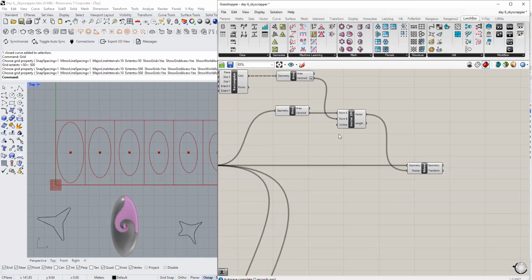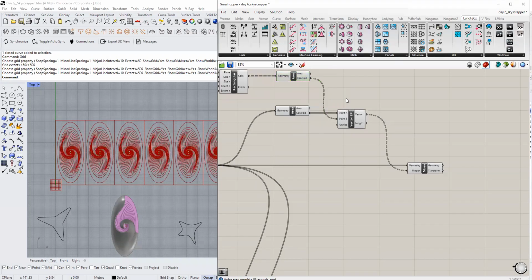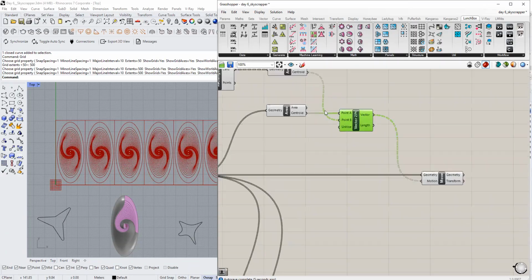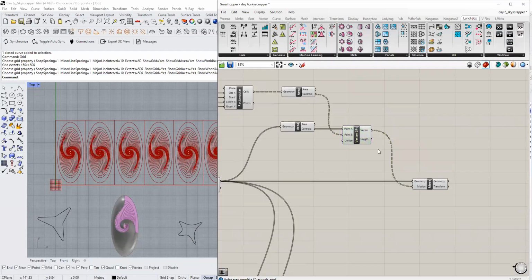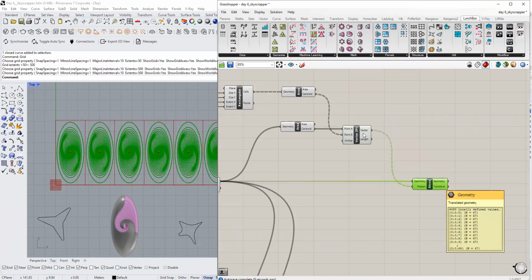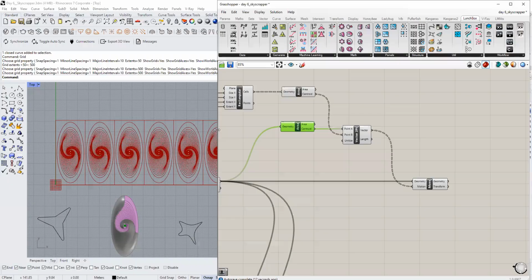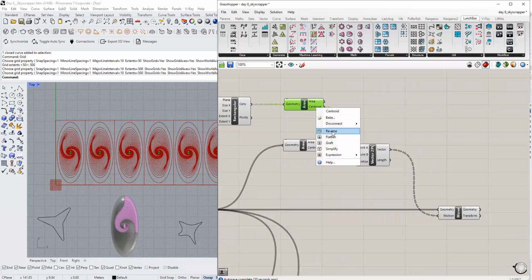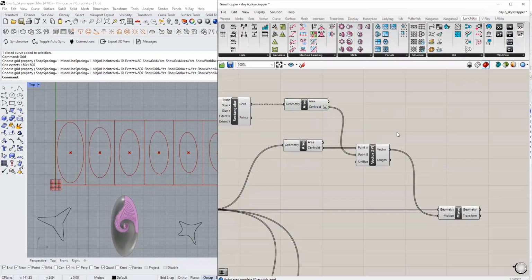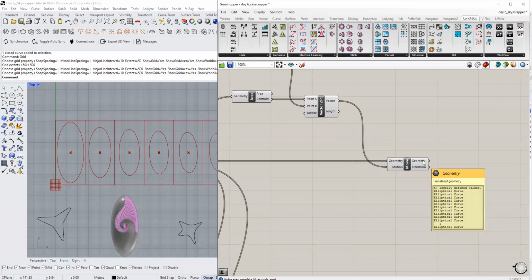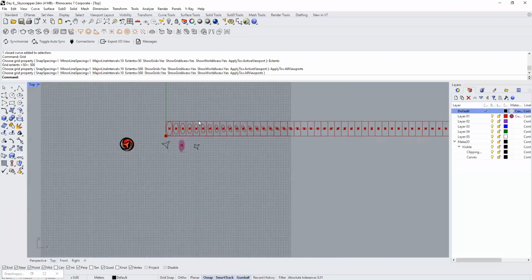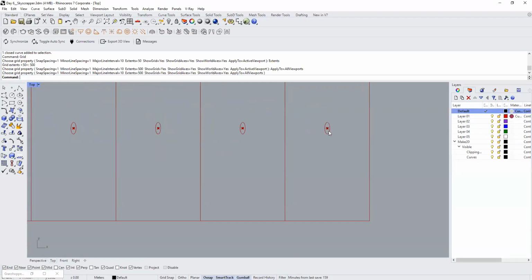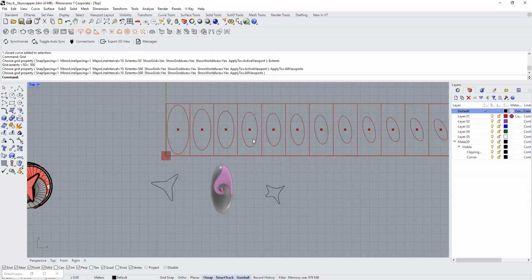That's it. So as I said, when you see this problem in multiple components, you can either go with a hunch and sort out the first component where you notice two different data structures, or you can retrace the steps from the last, go back, go back, go back. If there are multiple components, retrace and see which component has created that additional number of outputs. So here, if I flatten it in the centroid, this one automatically is sorted. And now if I look at the number of moved flow plates, it's 67. I zoom out, each cell has gotten one single flow plate. That's it, it's properly set.